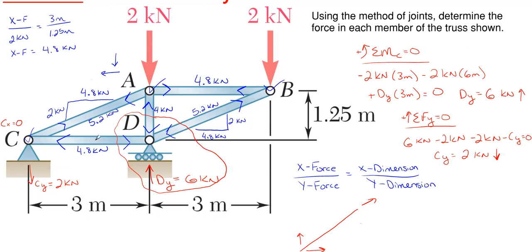Well, this 4.8 is a horizontal. There's my 2, and the arrow is down and to the left, so that means it's going downward. So in equilibrium here, I would have 6 up, 4 down, and an additional 2 down so that they cancel, and I would have equilibrium in the vertical direction relative to D.